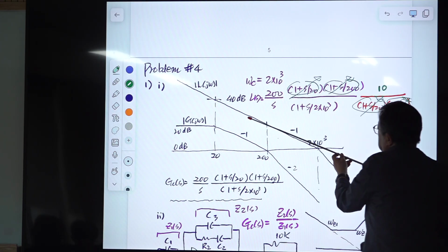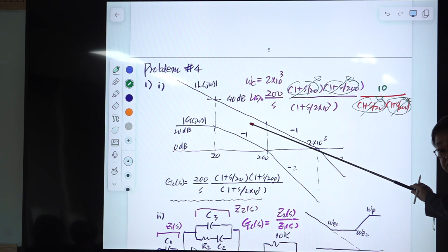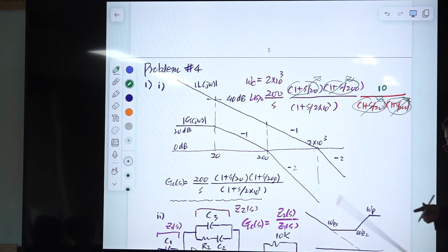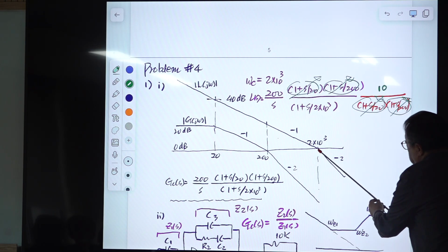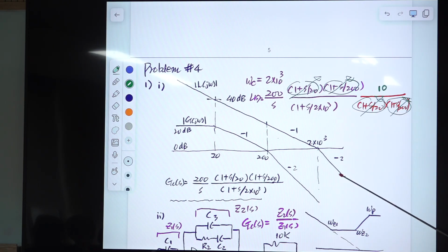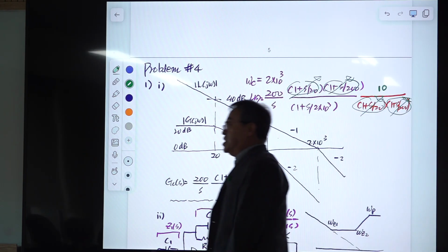Okay, if you don't put a pole here, this is more desirable in some sense, but high frequency noise becomes a big problem. At high frequencies, the noise is in the form of ringing and spiking, so it contains a lot of high frequency harmonics. So you need attenuation at high frequency here. Eventually it goes down rapidly. So you need to have a -1, -2 slope or -3 slope, something like that. For that purpose, you need to have one pole here,